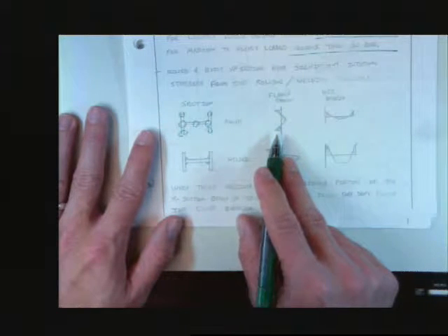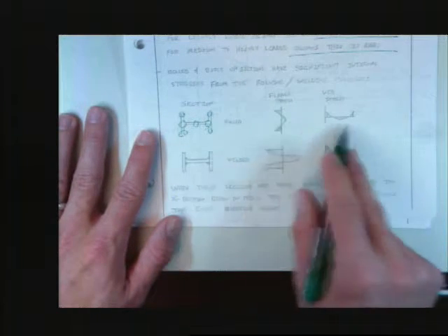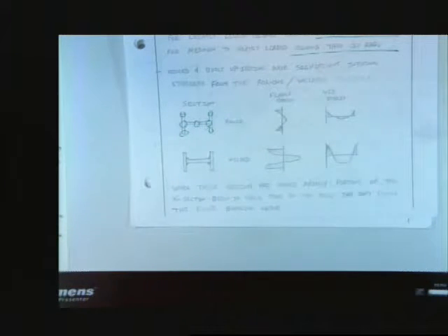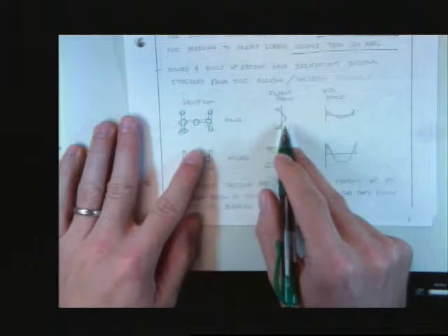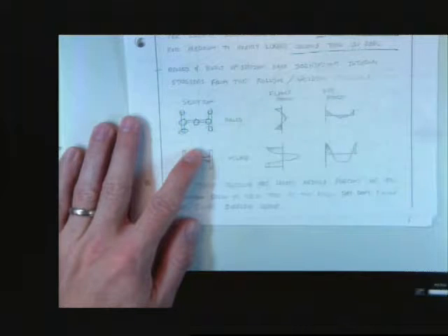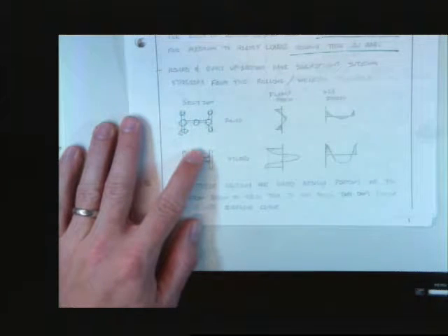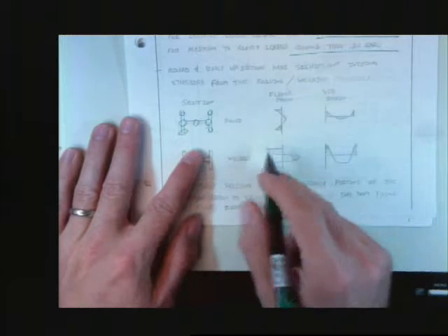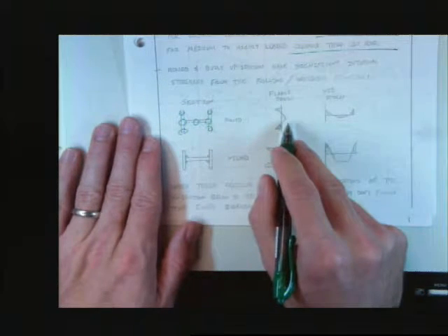Built-in stresses. It looks something like this on the bottom flange. You say, well, what do you mean built-in stresses? I mean, if a steel shape is sitting on the countertop here with no load on it whatsoever, what's the overall stress? It's not flying through space. If it's not being loaded, the stress is 0, right? Has to be 0, right? And it still is. But these residual stresses cancel each other out. If you have high amounts of compression in some areas, you have to have high amounts of tension in other areas. So again, they cancel each other out, but they're still there. They still exist.